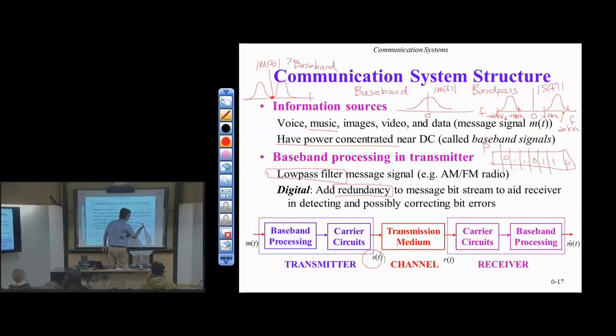So this would be now, in total, 8 bits. And the parity bit could be either odd or even parity, but just as an example, if I have an even number of 1 bits, I can call this 0. And in the receiver, if I look at this 8-bit value, if 1 bit has been flipped, the parity will be wrong. And I can detect that there's been a flip of 1 bit.